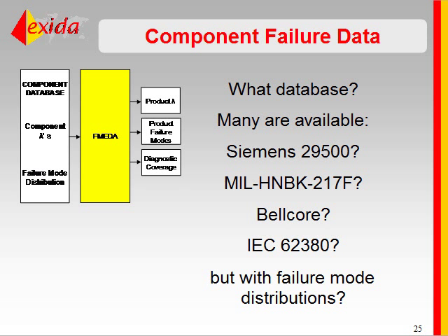Given that it's so important, where do we get this data? There are many component-level databases available in the world today. Some of you would recognize the Siemens 29500 database. It's primarily electronic components. The old Mil Handbook 217F was the primary standard back in the 80s when I learned some of this stuff.